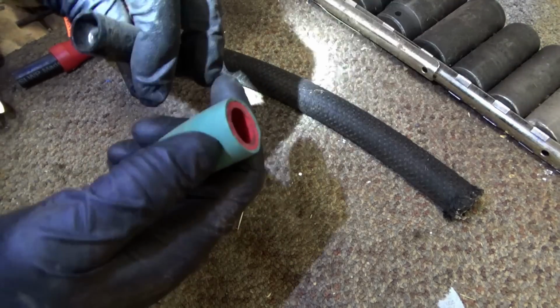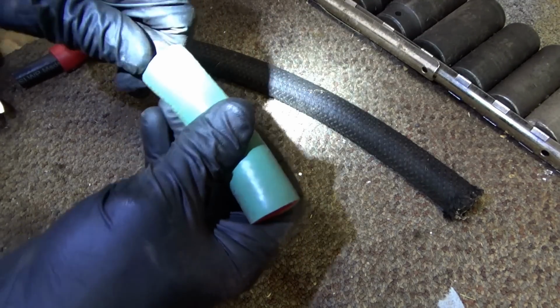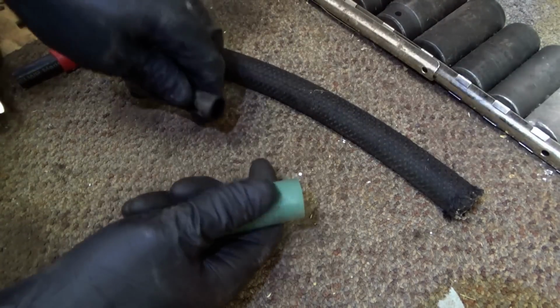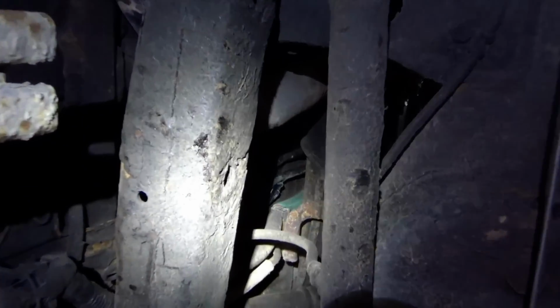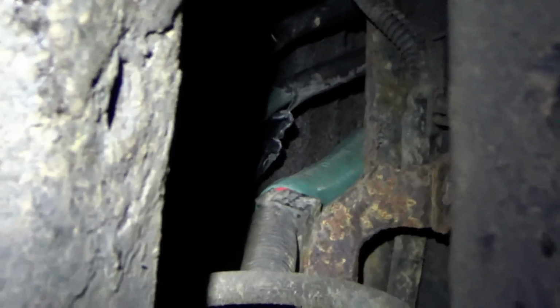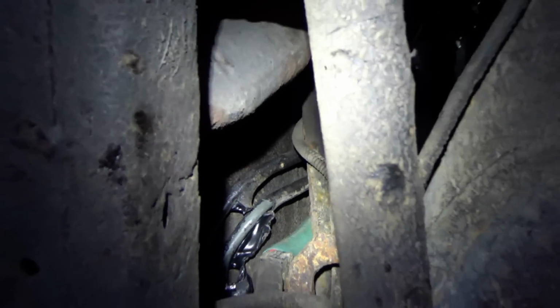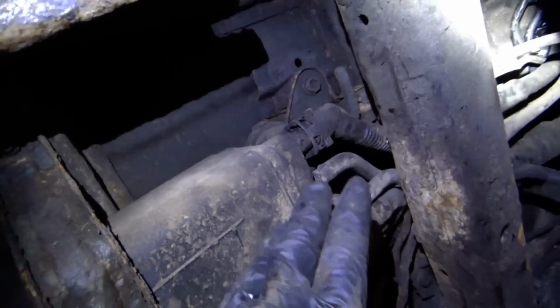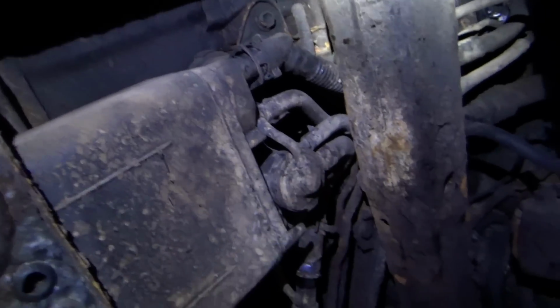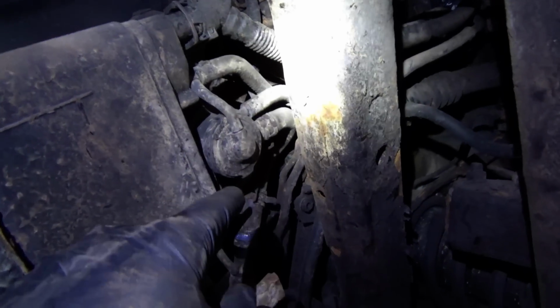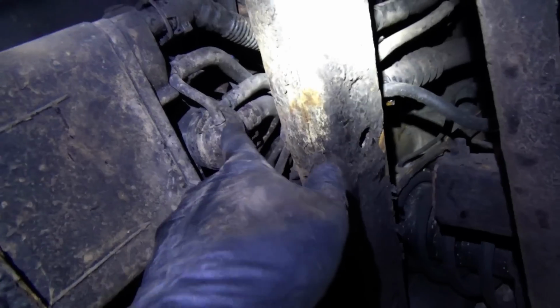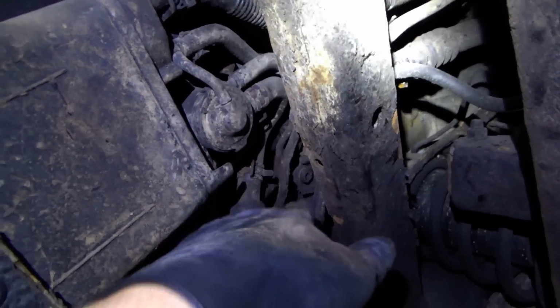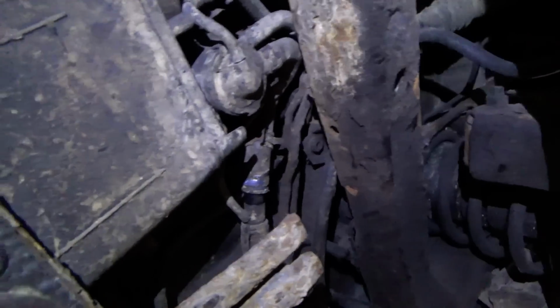I ordered a new Standard Motor Products solenoid for the canister. Should be good to go. Okay, final shot of the repair. There is the replacement silicone hose connecting the two plastic halves. And then I ordered the new valve. We'll put that in. But let's turn on the smoke machine and see if everything is leak tight. So the smoke should be coming in through this drain to the filter over there. Then we can squeeze this hose and see if the system builds pressure.